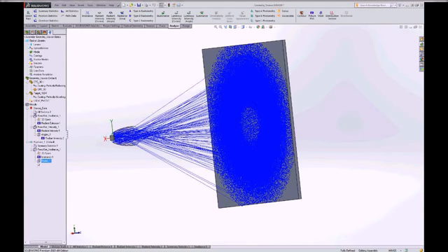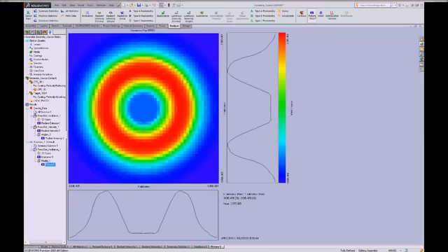Now, all this did was create a new data set, and you might have noticed, I didn't mention it, but before we did the averaging, more of the visualization tools were available to us, because the visualization tools can work on this stored data set, which can be, by the way, exported as an Excel file if you want to do post-processing on it. But what we'll do now is take this average data set, and again, I can look at a false color distribution, or if I wanted, I could look through it at a distribution section.